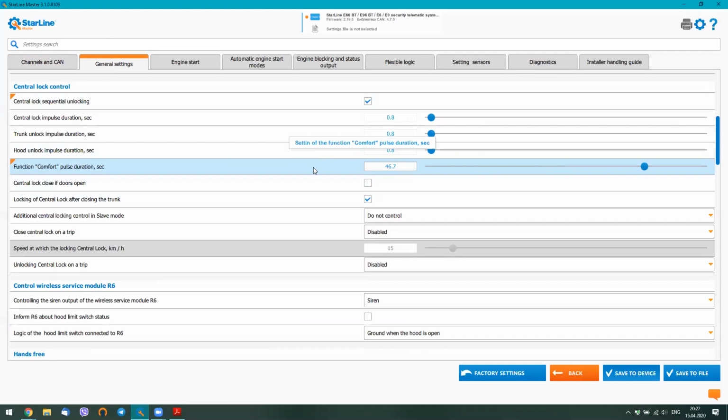On many cars, not all, you can use this wire to close windows. For example, if you connect it to the door key cylinder mechanism and lock position. If you insert a key to a door, rotate it to lock position and hold for example 15 seconds, usually it closes doors and windows. So you can use this connection to the door key cylinder and set the time you need for this car.